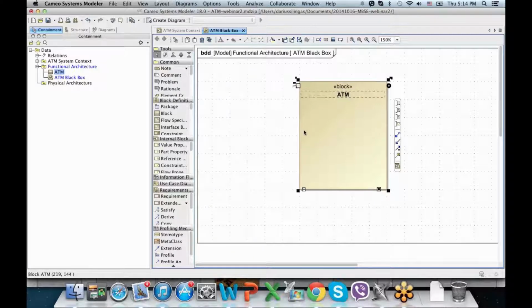The easiest way to create it is probably by selecting the ITM in Cameo Systems Modeler, and then choosing from the Smart Manipulator, which is the name for this UI element shown here on the right, and adding it to the system. You see here a label proxy, and it also gives me some name. For example, I will say this is customer operations. I would like to have a port which provides customer operations here. And this is a proxy port.